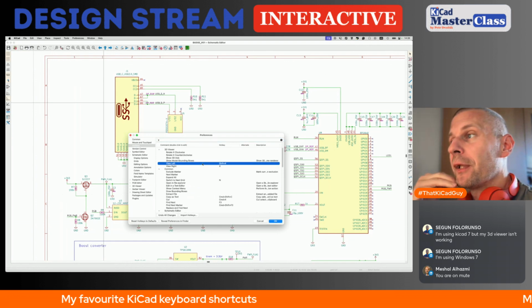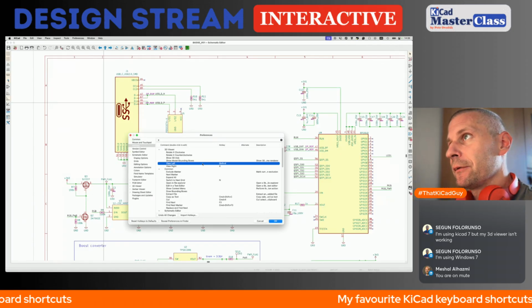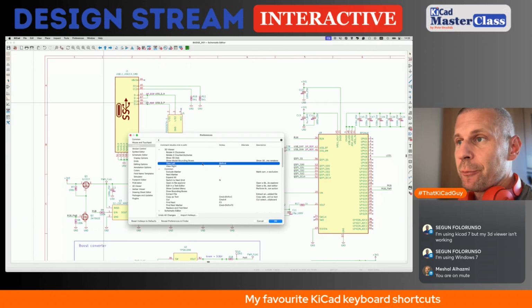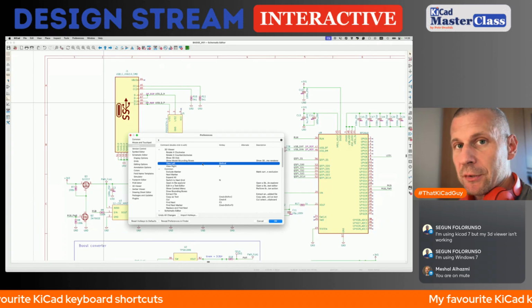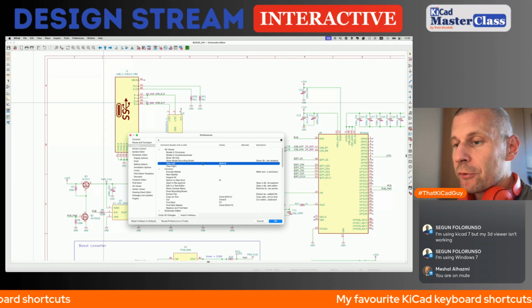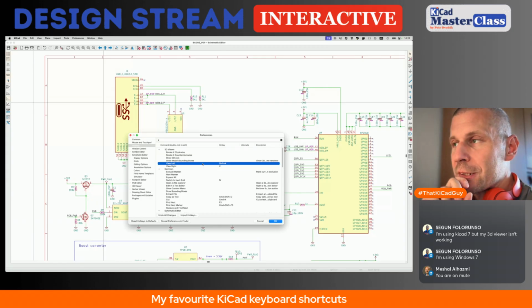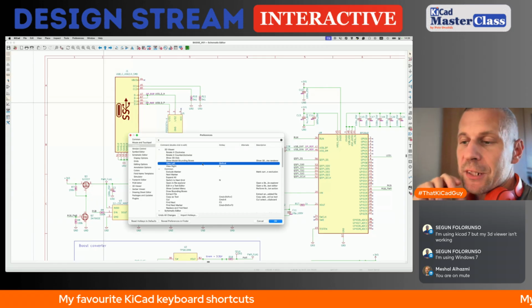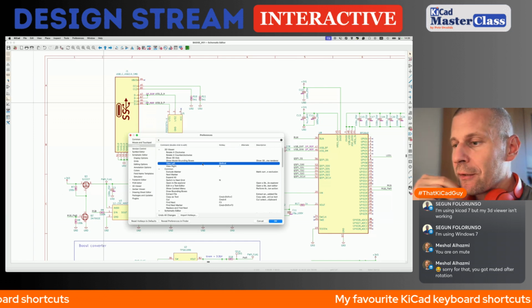because when I'm placing components or looking at the PCB layout, I sometimes accidentally change the context to the schematic editor, and when pressing X to start routing in the PCB editor, I accidentally horizontally mirror the symbol in the schematic without noticing. For resistors, it doesn't matter. For symbols, it doesn't matter.